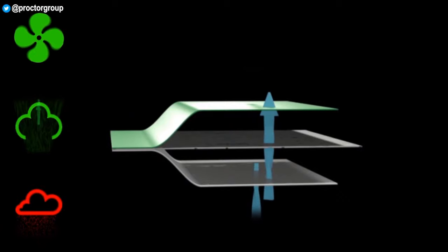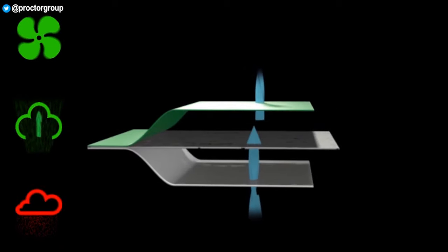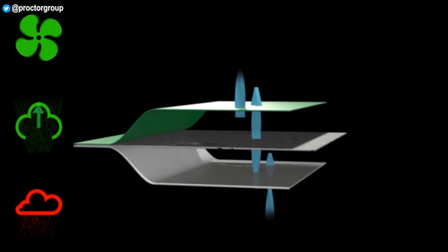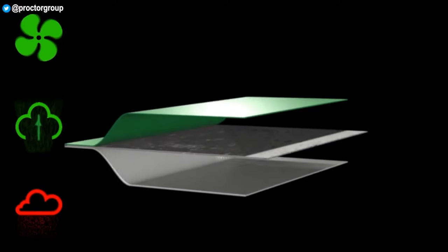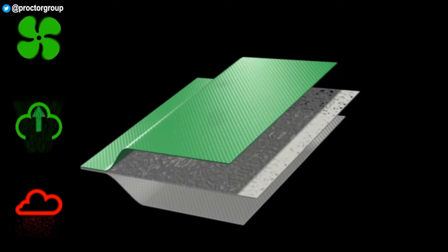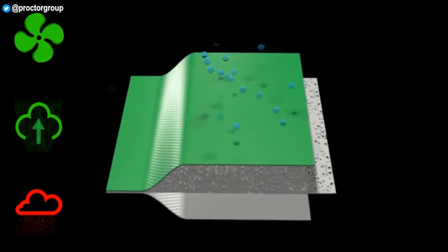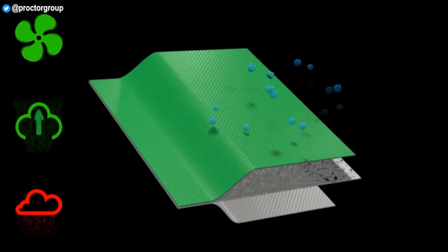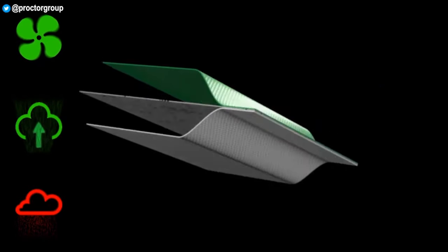This type of membrane has the most open structure and hence the highest permeability to water vapour. The open structure also allows air movement through the membrane, which boosts the rate at which vapour can escape a roof and significantly reduces the likelihood of condensation occurring. The relative weakness of SMS membranes is their water resistance, which, although more than adequate for their use on roofs, is lower than that of other membrane types.